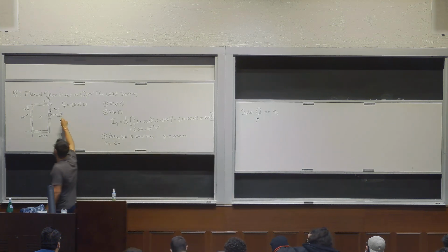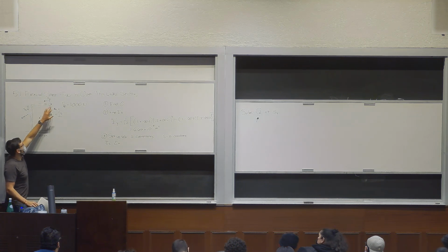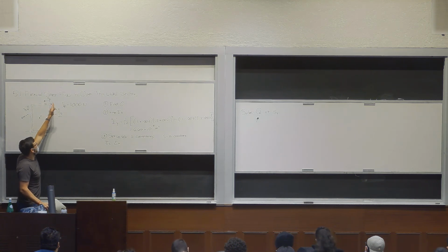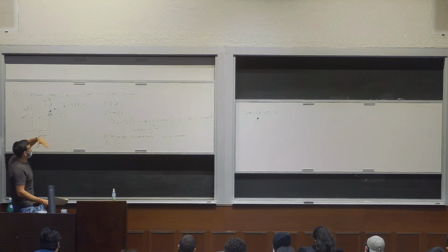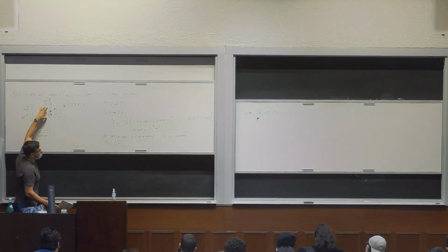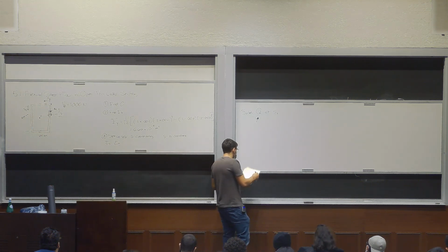From here to here, we found what big Q could be, the first moment of area. That value is going to be the starting point for S2, and then you're going to add more first moment of area as you progressively increase here. So we're going to start at the maximum possible first moment of area that came from S1. The equation for Q is going to be a little longer now.